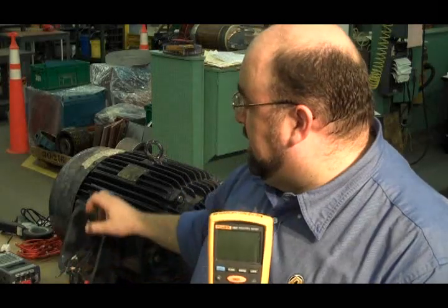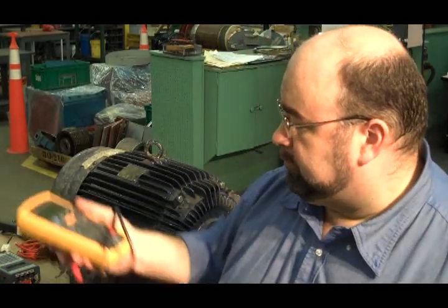The other thing I want to watch for, and most people don't realize this with insulation resistance testing, is that I can tell if I have a damp winding or a lot of contamination in the winding or a dried out insulation system if, while I'm doing the test, it climbs, decreases, climbs again and decreases and so on, because what I'm having is capacitive discharge. And capacitive discharge occurs when I do have a short that builds up to a threshold and discharges, builds up to a threshold and discharges, and so on. If I see that, then I have an insulation problem.